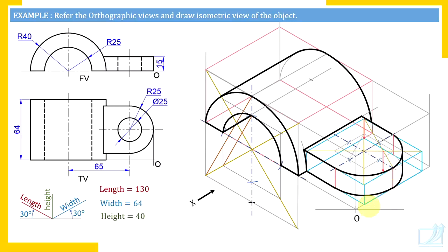Check, I have constructed the rhombus, and here we want to draw a complete circle. So join one end of the shorter diagonal. Longer diagonal and shorter diagonal are already present. So join one end of the shorter diagonal with the midpoint of opposite edges of this smaller rhombus. Now your focus must be on this smaller rhombus. Remember, in manual drawing, you are not allowed to erase all these construction lines. So don't erase the construction lines. Draw construction lines very, very faint. And only the edge is dark. All other lines must be faint lines. Only the edge is dark. Okay.